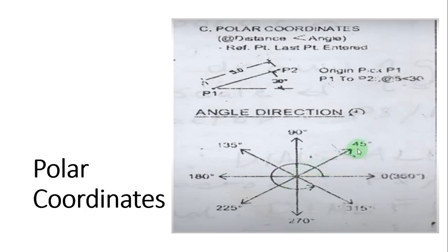If we create a specific line pertaining to the angle or the direction, we have here the guidelines. If we want to create a straight line from this point to the right, we include the length of the line, then the angle 0, to form a line. If we want to elevate it from 1 degree up to 89 degrees, we indicate the length of the line, then the angle in degrees.